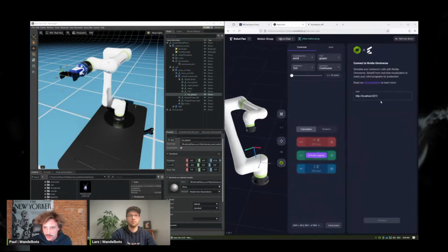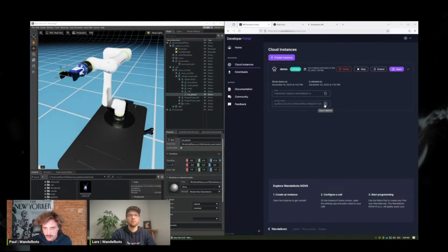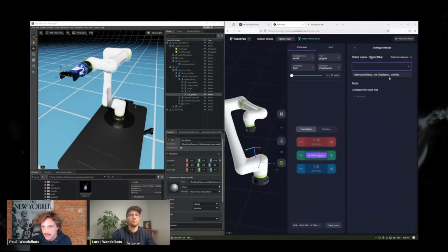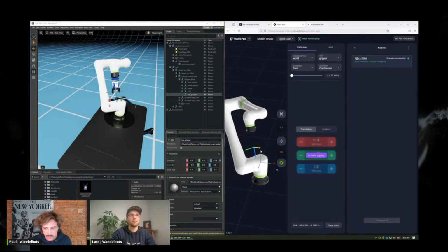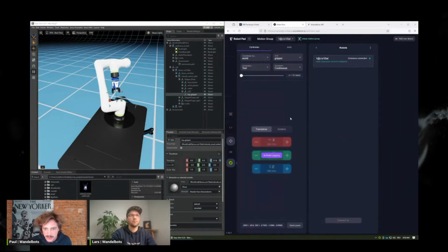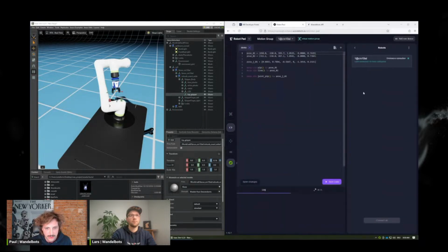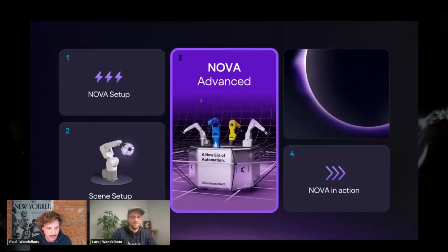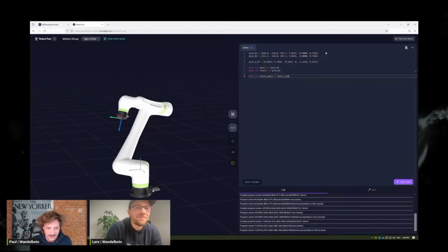And when I'm switching to tool orientation, you can now also see that this red, green, and blue arrow are facing the same direction as in Omniverse, in Isaac Sim. To see this, we have to connect. And now we can see that the TCPs are perfectly aligned, and we are good to go to start teaching with this tool. No, we are not. We have to set up something more. I'm sorry. No problem. I was a little bit quick here.